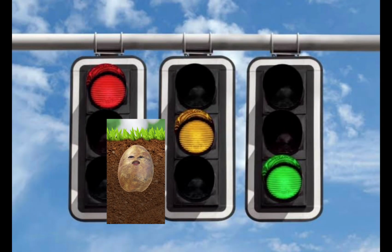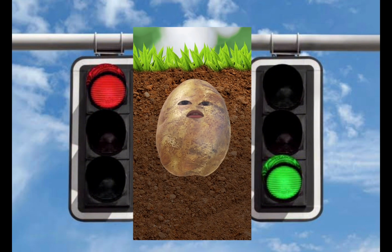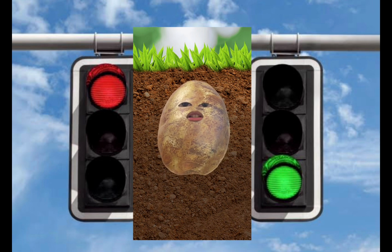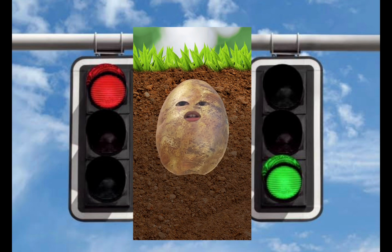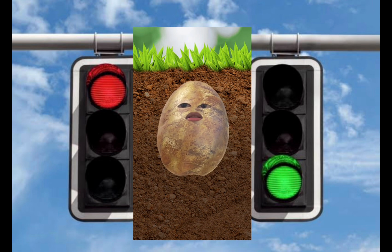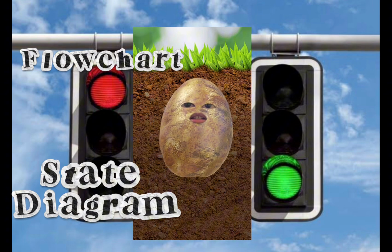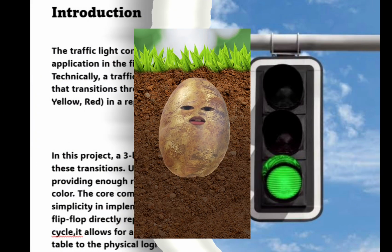Today, I will present my assignment about a traffic light system design. Traffic lights are very important in controlling the movement of vehicles at road intersections. They help reduce traffic congestion and prevent accidents by organizing the flow of traffic. In this project, I designed a traffic light system using a sequential circuit with D flip-flops. The design includes a flowchart, state diagram, state table, and sequential circuit design.